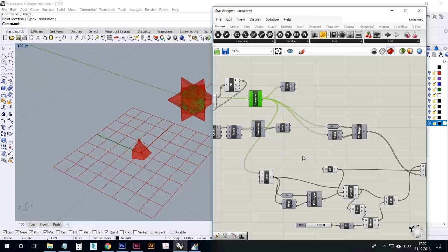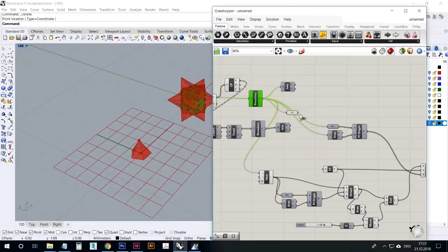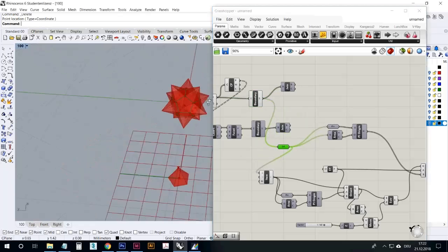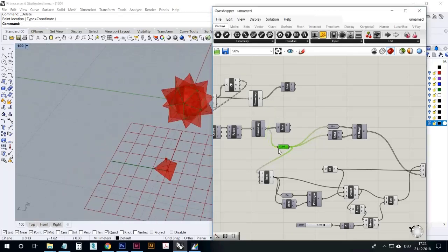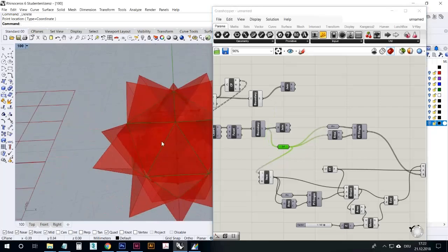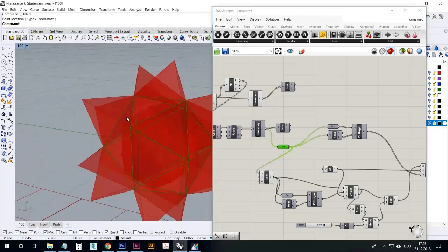So I want to plan my algorithm so that it's so easy as possible. So here we have a lot of surfaces. So if we instead go to geometry, surface, and we just replace things like this. Then we can simply swap shapes. And if I do that now, everything is going to be affected. This is going to turn into a triangle, and all these stellations is also going to be adapted accordingly. So if I just pull that in like that, you have already a stellated icosahedron. So I can toggle between these two in a very easy way.